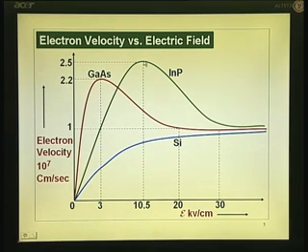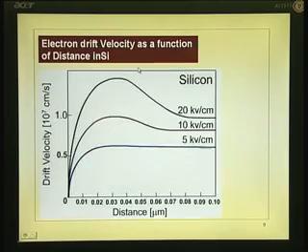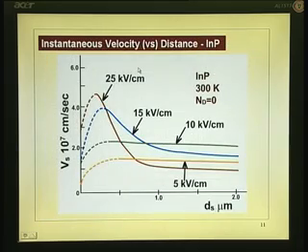Till that peak, we have analyzed and seen that the electrons are always in the lower valley. So, if you suddenly apply a field equal to 10 kV per centimeter in the case of indium phosphide, it is never going to go to the upper valley. It will go on increasing, and it does not experience that transient so much. So, that is why you see that particular effect there.